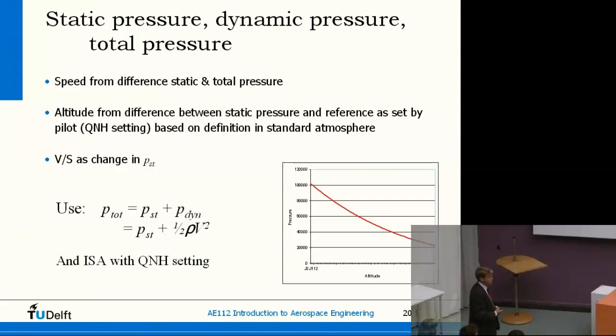The altitude difference. You measure a pressure, but you do not know what the pressure at sea level is normally. You don't have an instrument to measure that, and this varies during your flight. So that's why normally we assume a standard reference atmosphere, and at sea level we assume the standard level during our complete flight, because all the aircraft take the same reference level, which means that relative to each other, we always have the correct altitude or altitude difference.